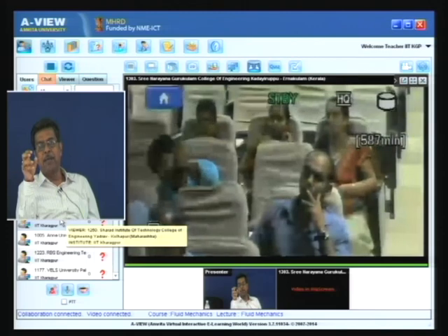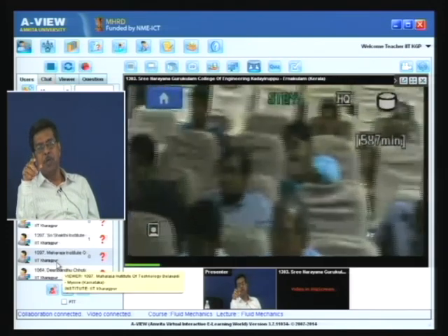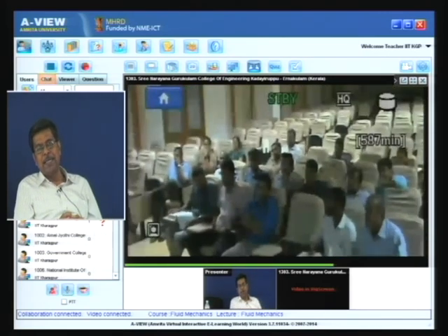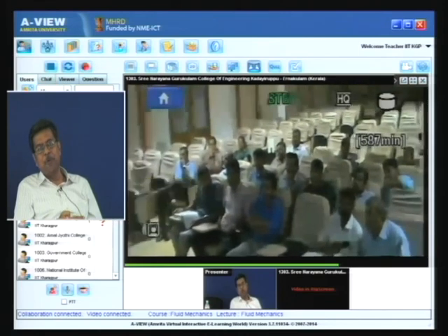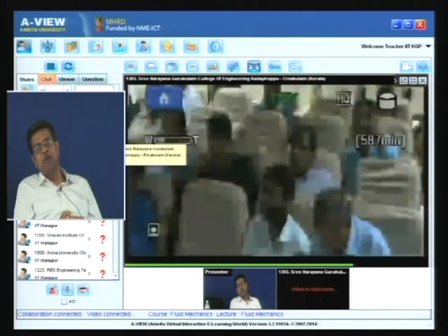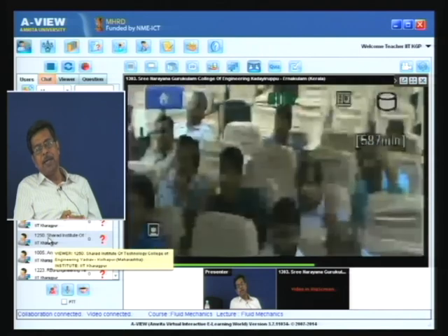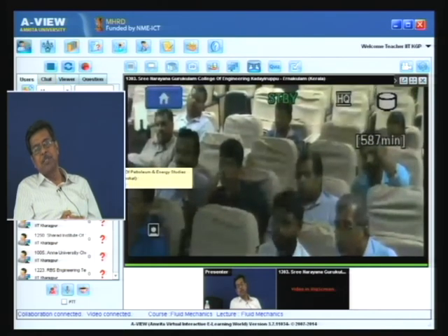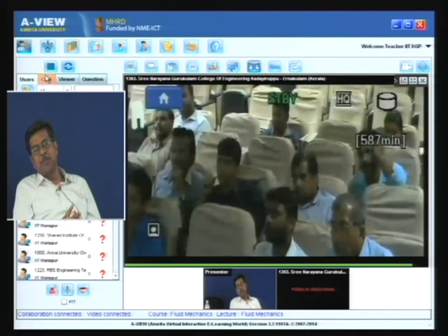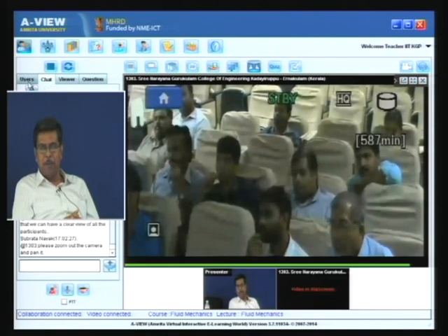That is the volume flow rate coming through that limb. You just correct it. If the total flow rate is specified as Q, then the flow rate through any limb will be Q by 2, which is V_R dot n dA over the control surface, where the control surface is the area of the nozzle of that limb.